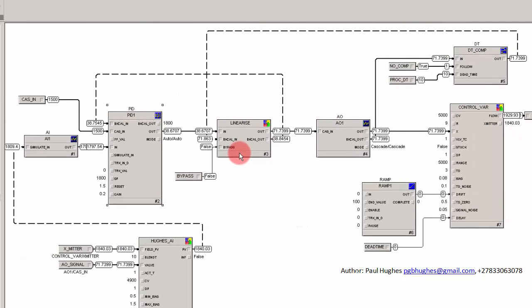So this has basically solved several problems which one sees in industry: low flow turndown, fallback on an estimated value, and nonlinear flow to valve lift characteristics, which is resolved using this linearizer block and mechanism. So solved several problems fairly simply in one fell swoop.